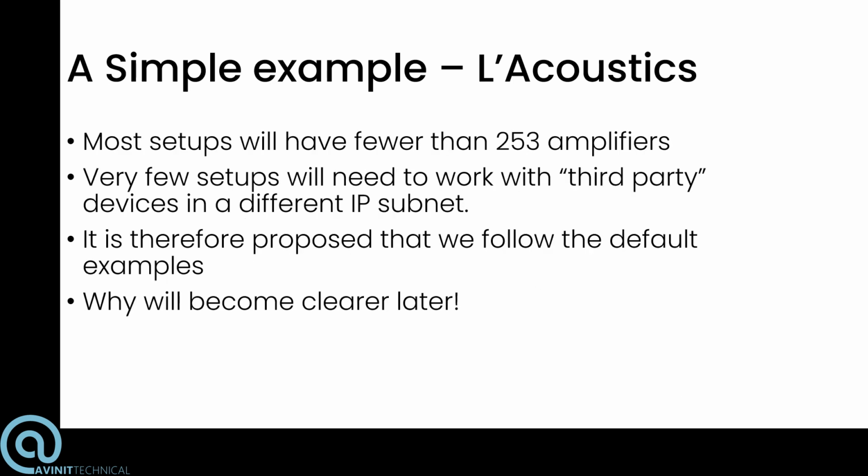So most setups will have fewer than 253 amplifiers. That's a lot of amplifiers. Very few setups will need to work with third-party devices in a different IP subnet, and it's therefore proposed we follow the default examples. This will become clearer later, but I'm declaring the assumptions we're making. Now, of course, if these assumptions are at variance with your particular implementation, that can be accommodated, but we're trying to keep things simple and using a generalization to make a specific point.